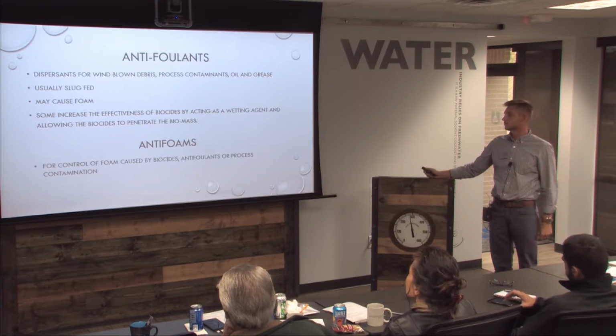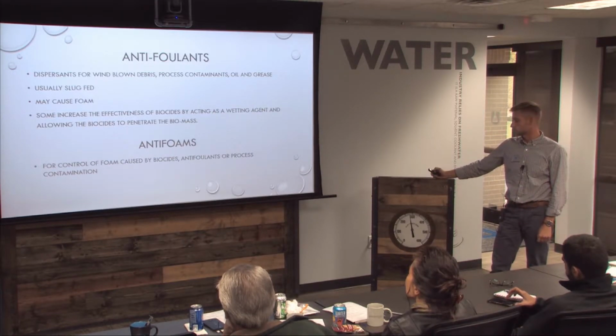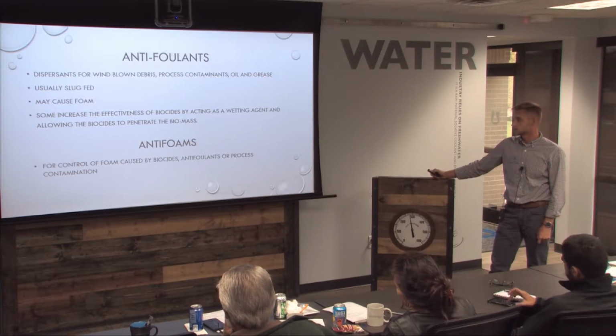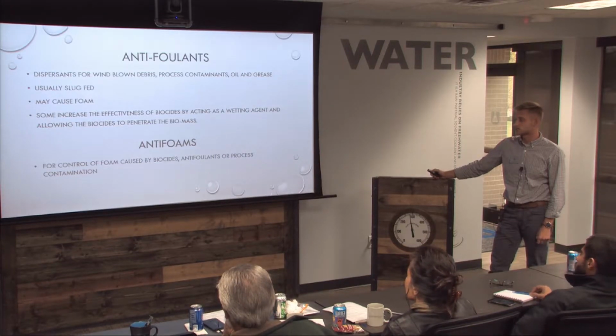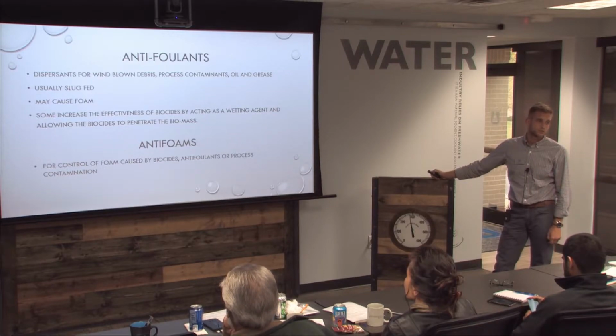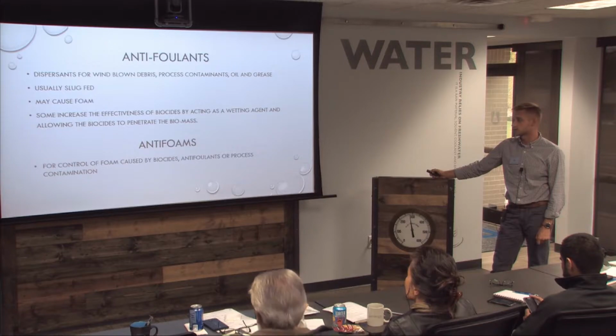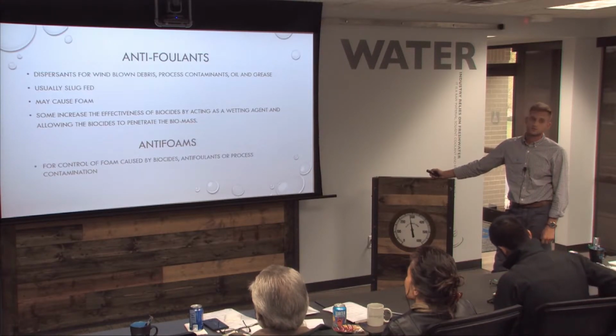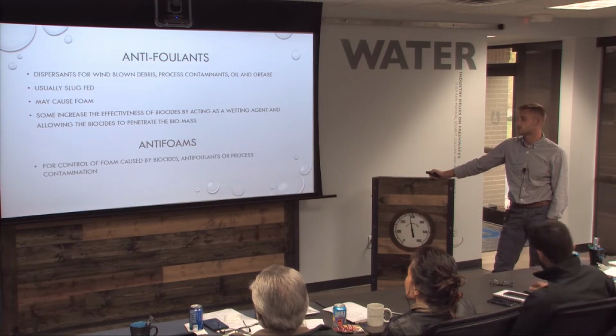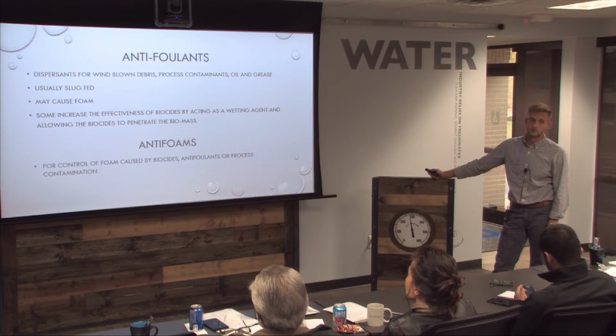And then defoamers, like we talked about, same reason for boilers. Introducing air into your system can cause major issues. But some biocides, when they're actually working, they foam. When it's attacking whatever's in there, it'll foam a little bit. You may need them. It's not overly common. We typically use anti-foams when we're descaling because it is attacking the scale. But if you have a foaming problem, you probably have a greater problem than just biocides attacking.